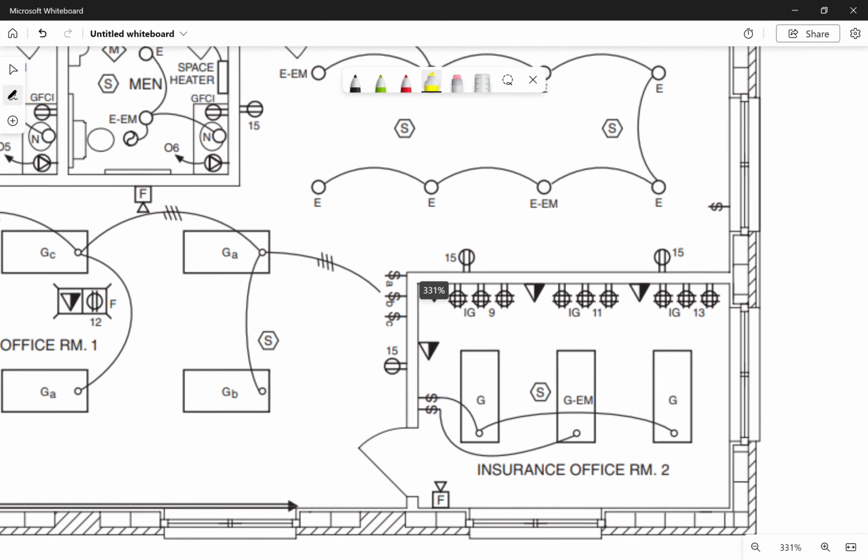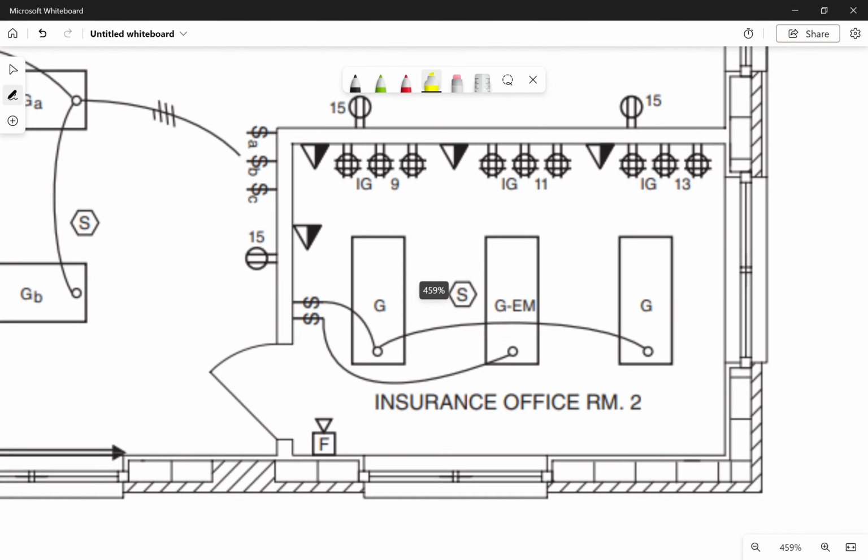Now we're going to do it both ways. We're going to figure the minimum based off of the square footage of how many receptacles that we have, but we're also going to count our receptacles and issue a minimum volt amperage of 180 volt amps per receptacle that we're going to use to also calculate. And the reason that we do that is because the minimum, it's a minimum.